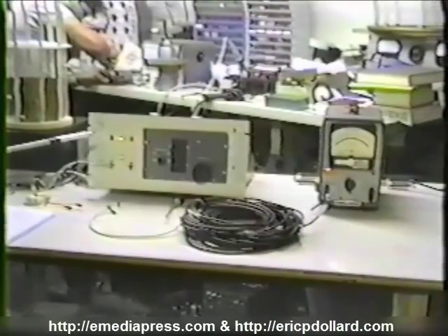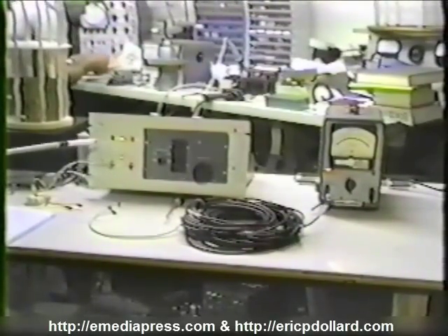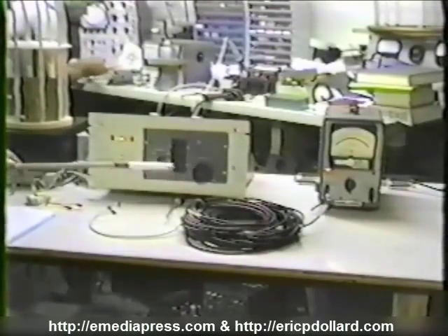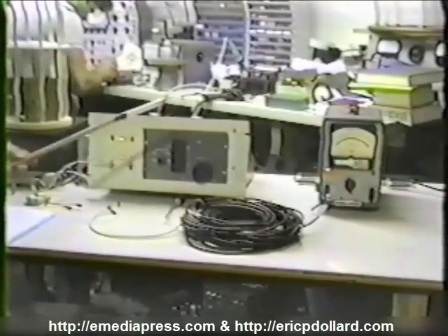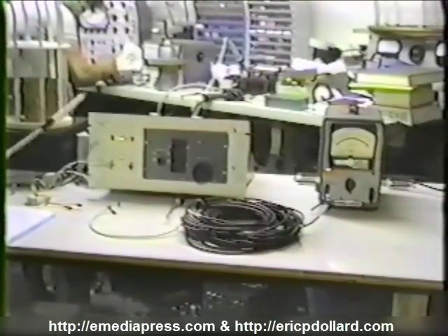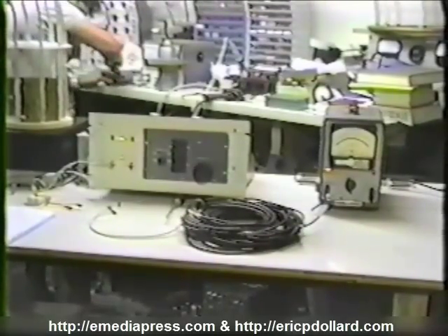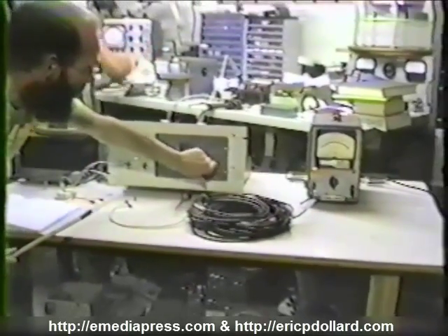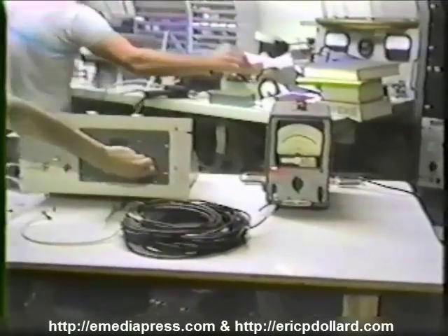The oscillator has gone through another 180 degrees of shift and is producing a right side up impulse to match the reflected, now right side up, impulse. And this process keeps on going until the voltage rises to a level where the losses of the system prevent any further increase. So what we're going to do is sweep the frequency here and find the resonance point of this cable to determine the propagating velocity.